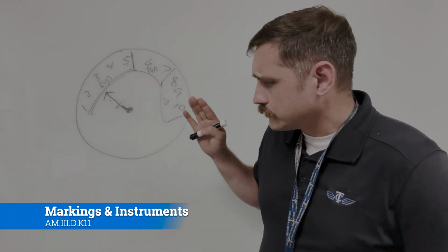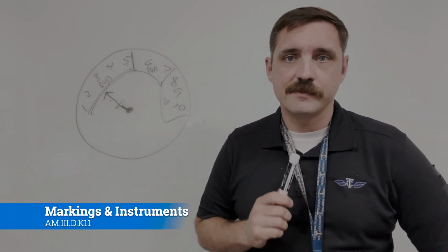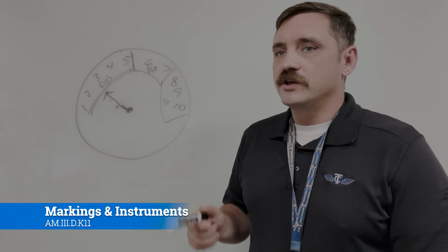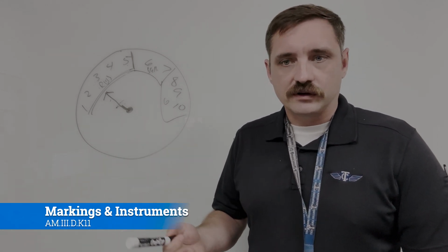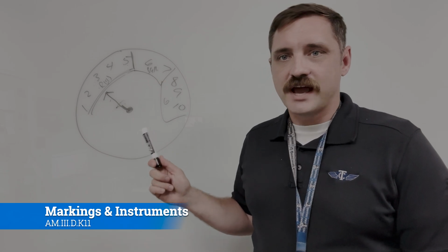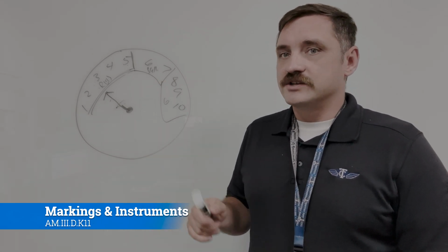Now, one of the things that will happen, and I've seen happen multiple times, is that you'll get a squawk that says, hey look, my engine oil pressure is low. And then whenever you go in there to look at it, the engine oil pressure is not actually low. What's happened is the gauge went out, and so it's just indicating error.